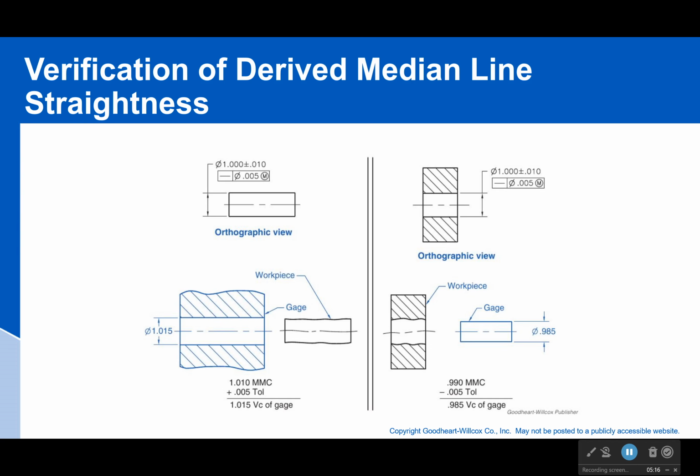Okay, now let's look at those gauges again so you can see what I was talking about and drawing terribly before. So a gauge is a part you might make that has a very, very fine tolerance. I mean, it's made as perfect as you can make it. And the thing is, you only want to do it once because you're going to check a bunch of workpieces. You only ever make a gauge if you're going to be testing something 1,000 or 10,000 times, and you want to do it quickly and accurately. So it's only good if you just need to check a bunch of pieces. Otherwise, you're wasting your time and money to do this.